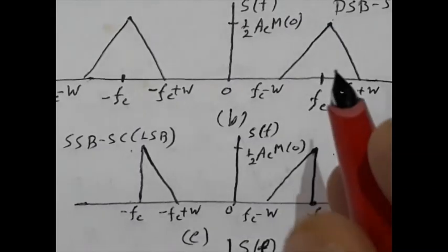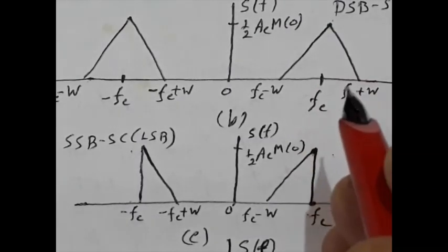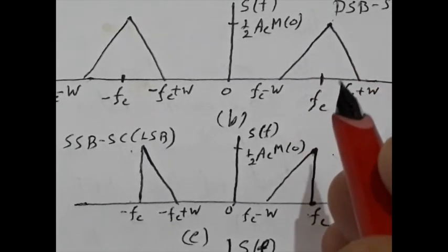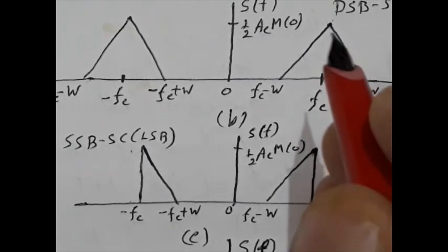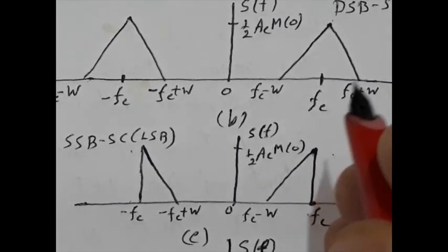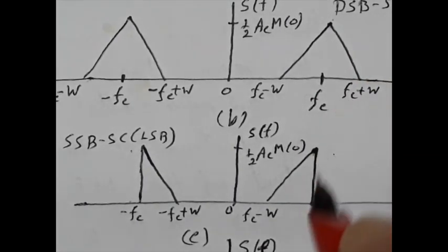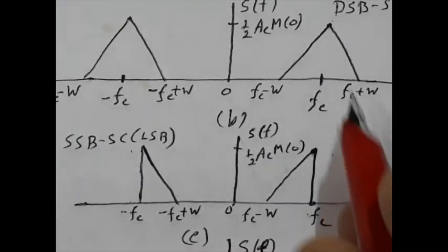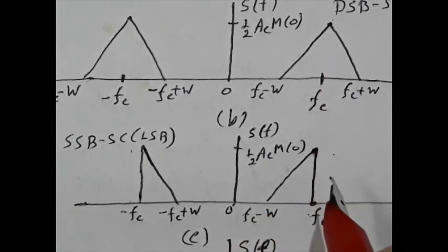That means we are not allowing all of the sideband, we are allowing just a portion of the other sideband. Portion means vestige. That is why it is called the vestigial sideband. So in this vestigial sideband, we will allow a small portion of the suppressed part of the sideband in this way.